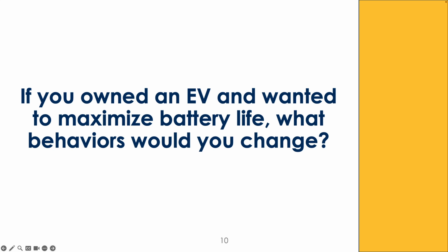What we said is to make sure we don't charge past, for example, 80% by setting the charger capacity there, and then to also make sure we end the trip before the battery drops below 20%, to make sure it's kind of in that healthy range.